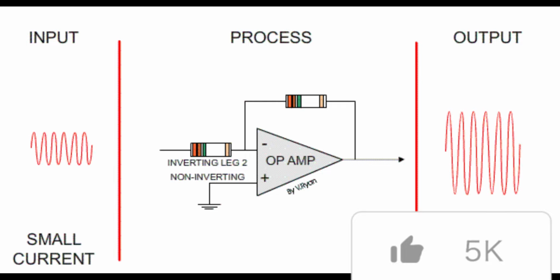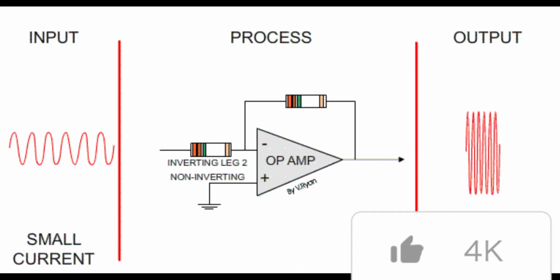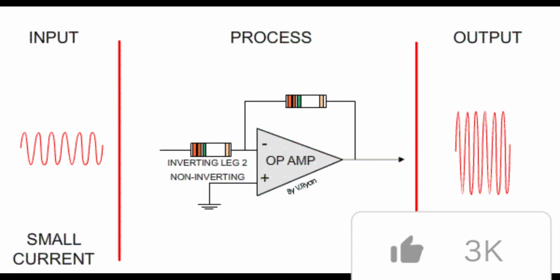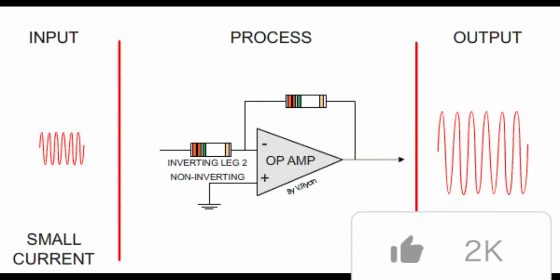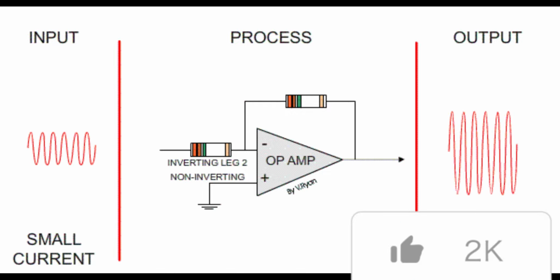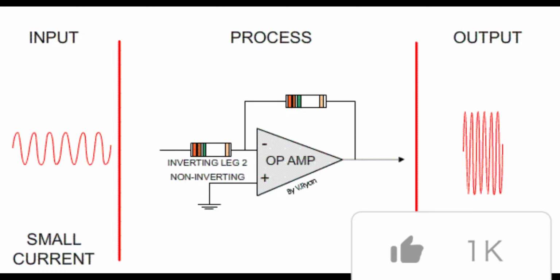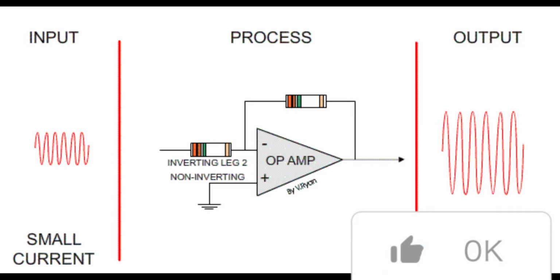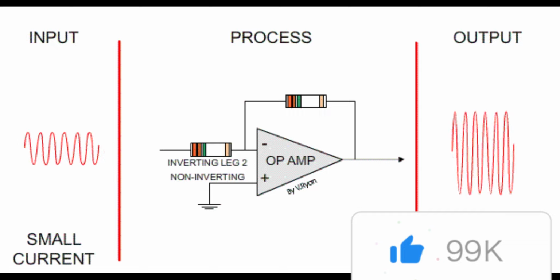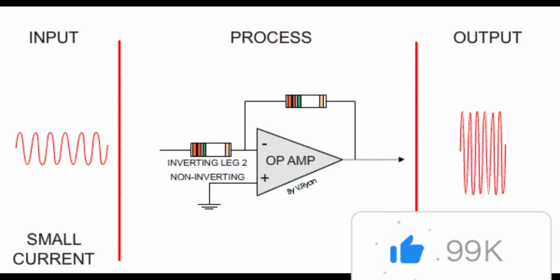Noise. The perfect operational amplifier will have zero noise. Unfortunately, all op-amps contain several internal noise sources, such as current and resistor noise, and more. They are measured at the output and referred back to the inputs. The equivalent input noise voltage is the most significant noise type, and it's also bandwidth dependent. Overall, designers should aim for this noise value to be as small as possible.